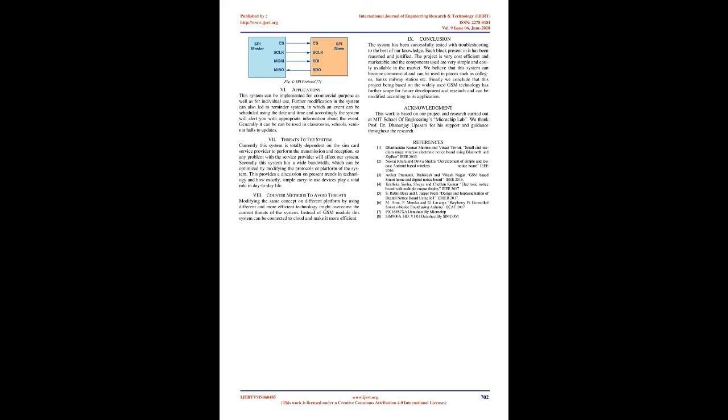In order to program the PIC microcontroller we need an IDE where the programming takes place. An IDE has a compiler, where our program gets converted into binary format. Using the bootloader protocol, the hex file, the executable file, is uploaded into the flash memory of the microcontroller.